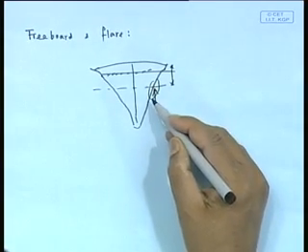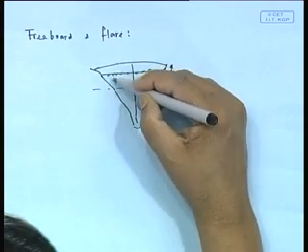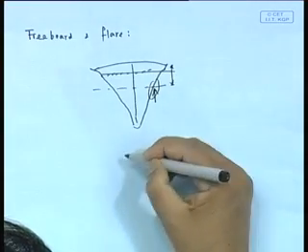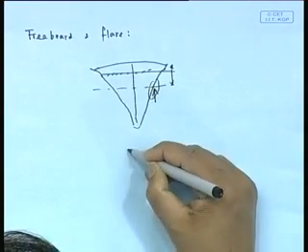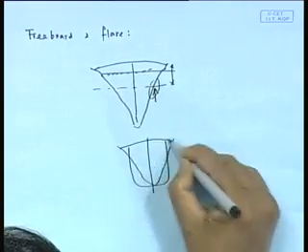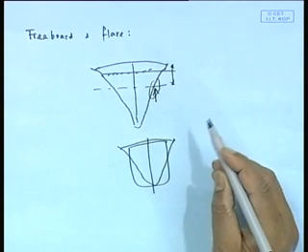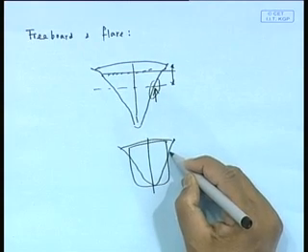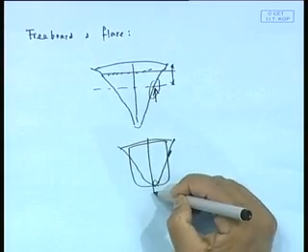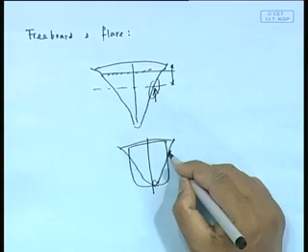So, what is happening is that this is actually a question of judicious choice. Should you take typically the U shape or a slightly V shape? They have competing effects. In V shape, the slamming is larger, basically bow flare slamming is larger, but bottom slamming is smaller. U shape, the bottom slamming is larger, there is no bow flare slamming. Bow flare slamming means slamming coming at this region.